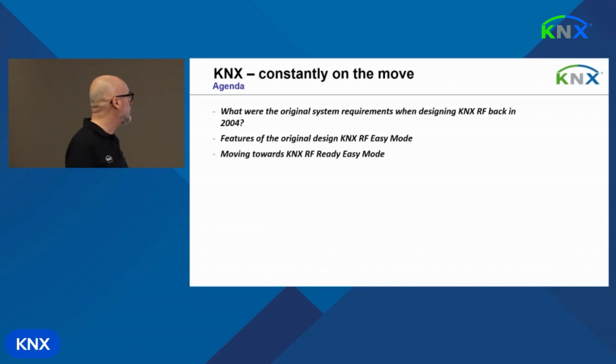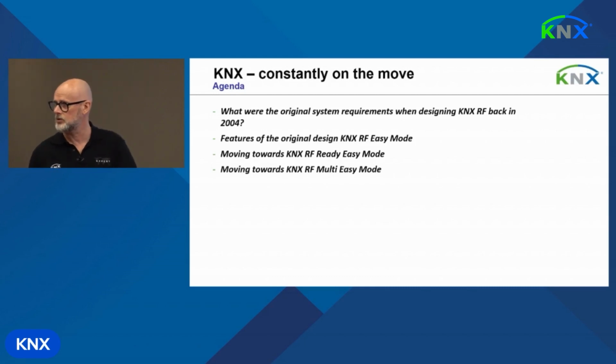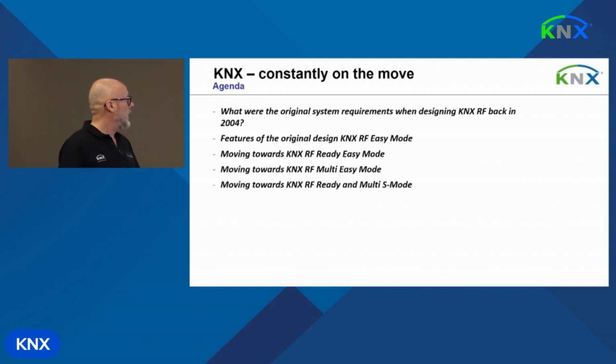Then we moved towards KNX radio frequency ready easy mode. Sounds a little bit the same, but there's one extra word, which is ready. I will explain what that means. Then KNX moved towards KNX radio frequency multi easy mode, and I again stress the word easy. And then we moved towards also being able to handle KNX radio frequency products in the ETS. That's why we moved towards KNX radio frequency ready and multi S mode. So in the ETS, then at that time, it was possible to, as a KNX installer, also integrate products in an ETS project.